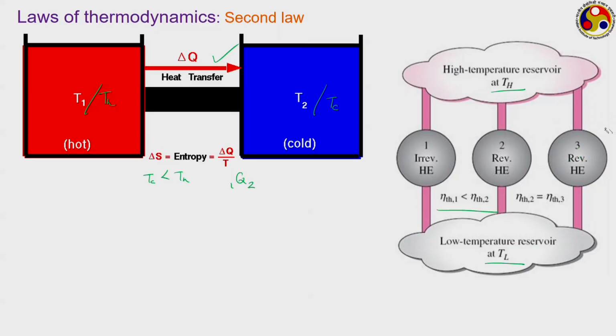So, that is the first Carnot principle, but here we are concerned about the second Carnot principle. Let us remove this one from our system. We have now 2 and 3, both are reversible heat engines and both are working between the same two reservoirs. Then the second Carnot principle says that both of them will have the same efficiency. That is, in more formal terms, the efficiency of any Carnot engine, any reversible heat engine, working between two given thermal reservoirs will always be the same.